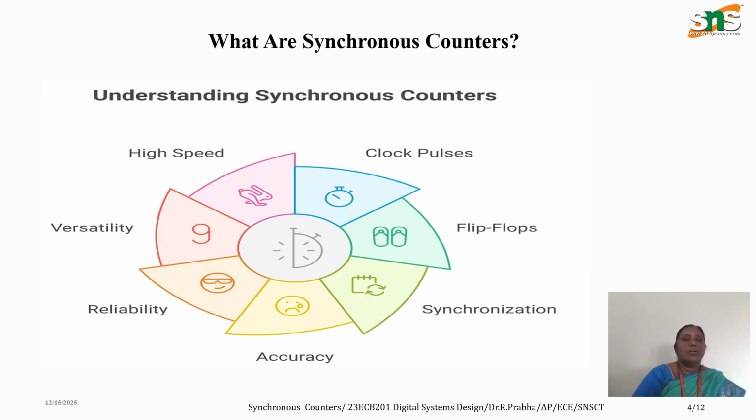In synchronous counters, a common clock pulse is applied simultaneously to all the flip-flops, which eliminates the ripple delay. Because of this reason, the synchronous counter is more suitable for high frequency and high speed applications.